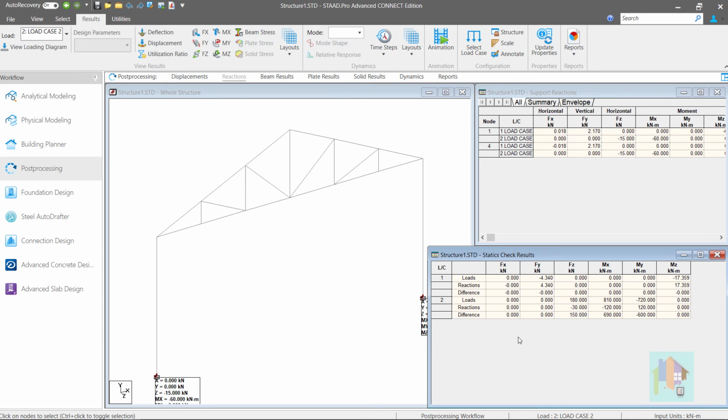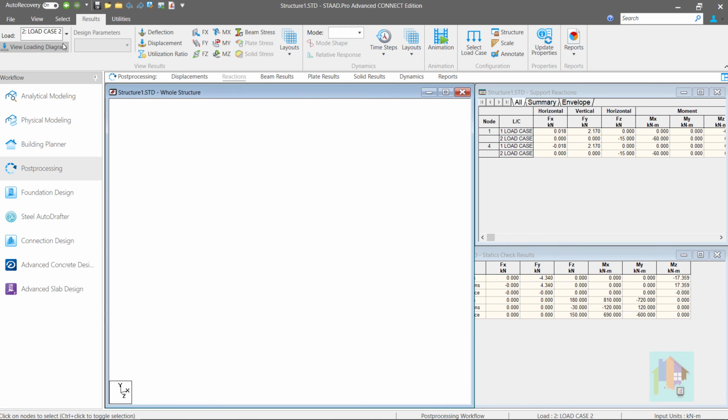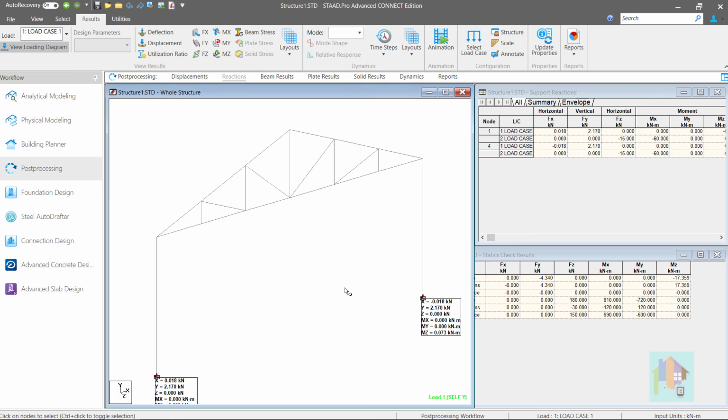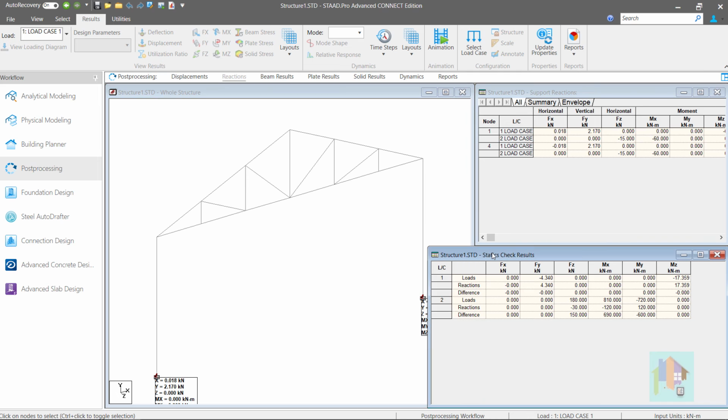The reason is this is a gravity load and no load is applied in the zero stiffness direction. Though the warning message is reported, for gravity load or any load which is not in the zero stiffness direction, we can ignore these warnings. For load case 2, the applied load is not equal to the reaction.